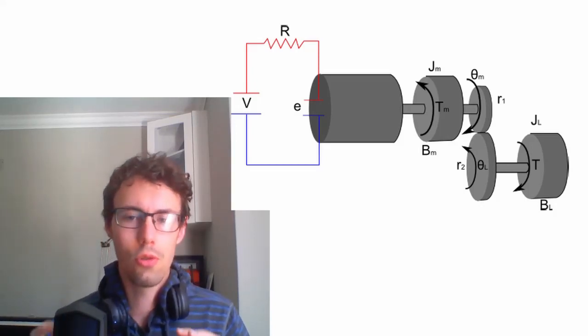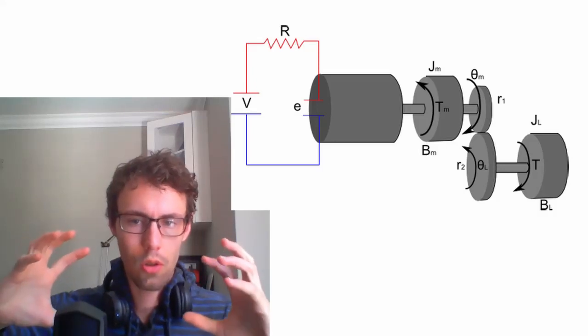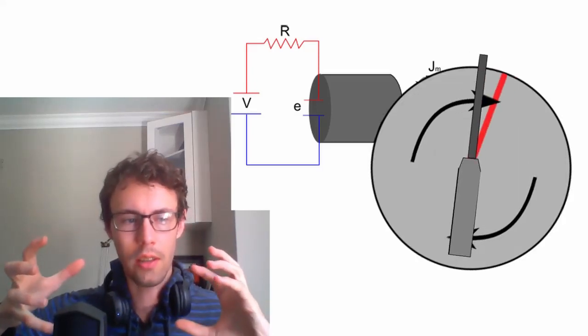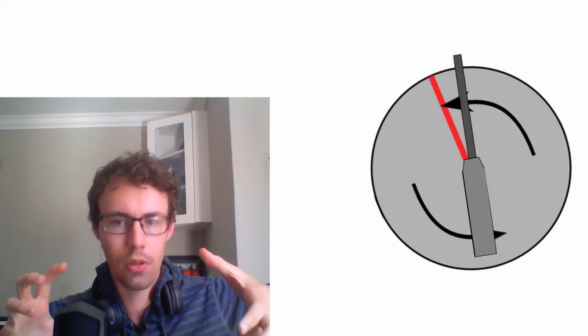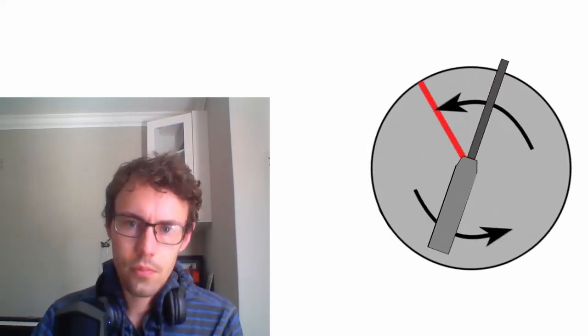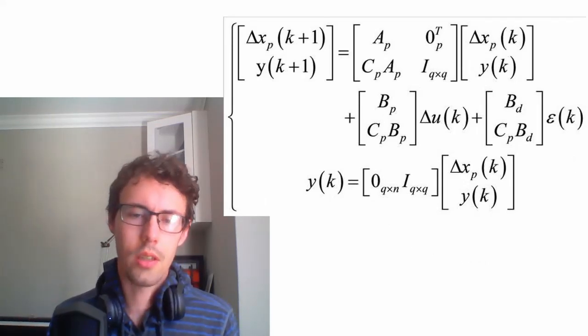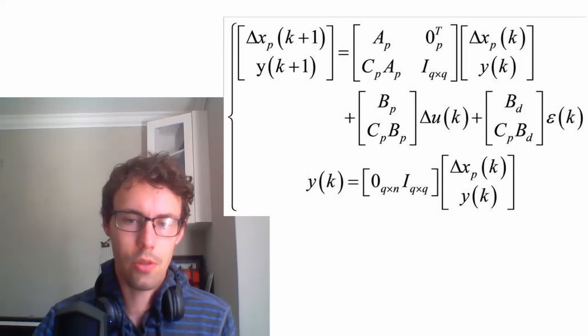So you work out the torsional rigidity, which means how much does the system flex, because if you quickly torque the motor on this side, then how long is it going to take for the turret to respond on the other side, and that's all going to influence the control system. So then you can build this mathematical model.